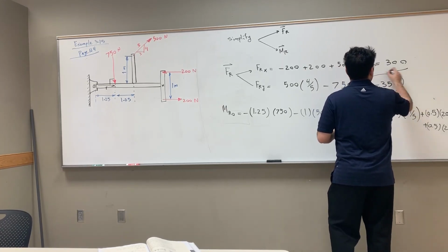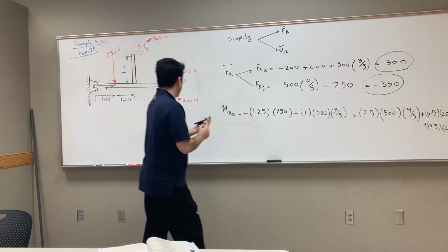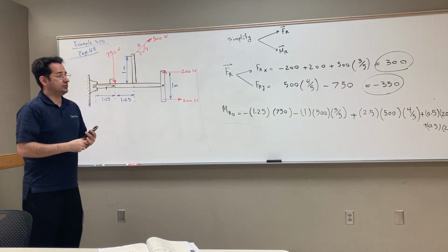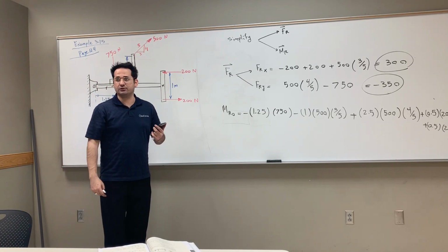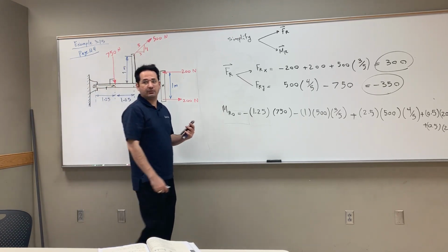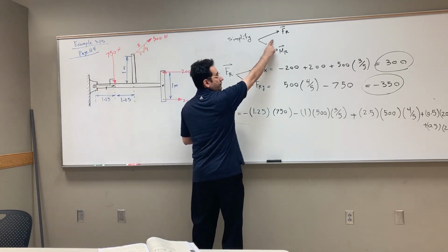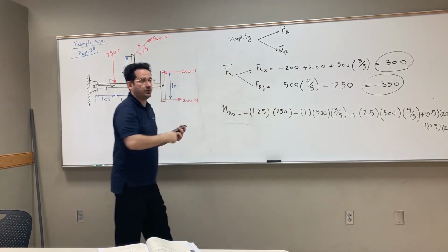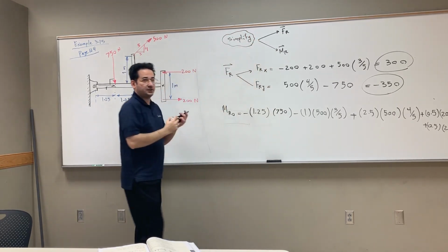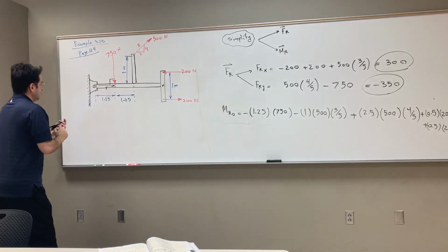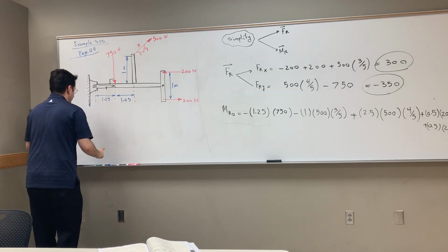This is the y component of force, this is the x component of force. So I'm ready to replace all these forces, no matter how many forces and moments you have in the system. I'm now ready to replace it with one force and one moment at that particular point. And this is called simplification. This is this section, simplified, right? So let's try it one more time.